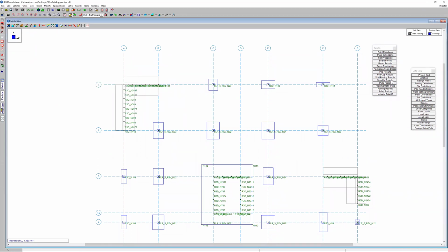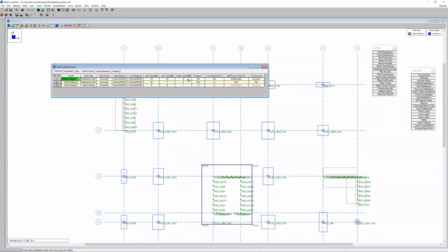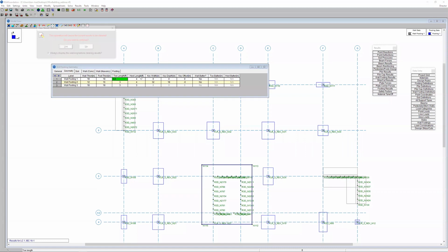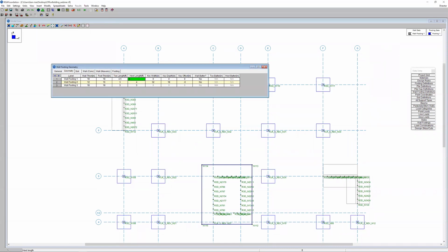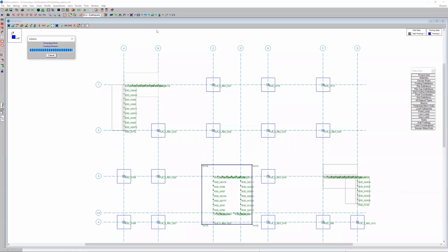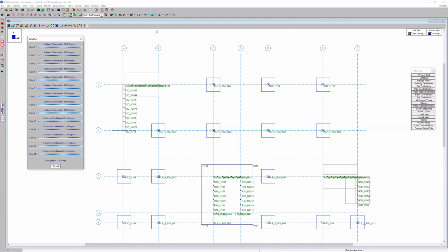And if we look at our wall footing design rules, basically we can see the geometry of this. The footing thickness is 18 inches, toe, so basically it's 7 foot. Let's go ahead and change this to, I don't know, 4.5, and 4.5, and we'll lose results, and that's okay. So a little bit bigger should hopefully allow us to solve a few of our bearing capacity problems, right? And so we should then hopefully get some design for these different retaining walls.